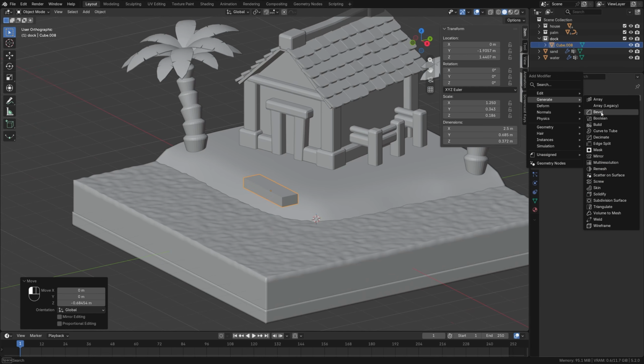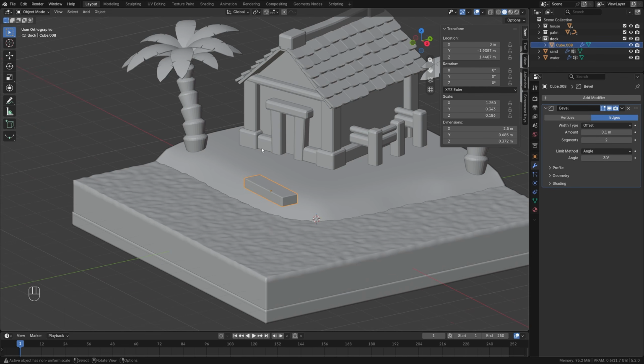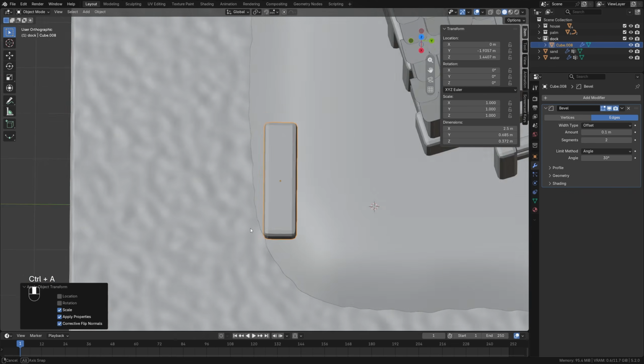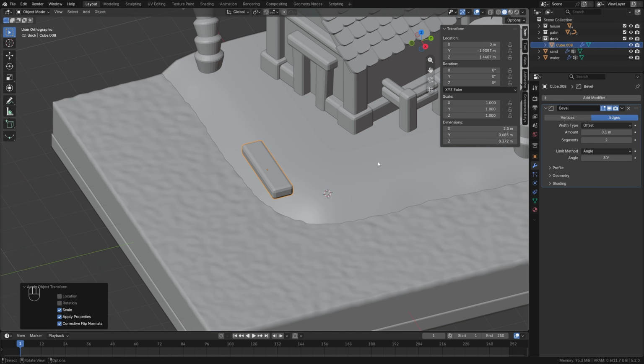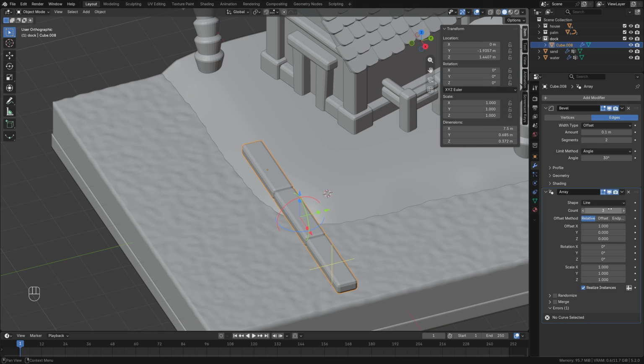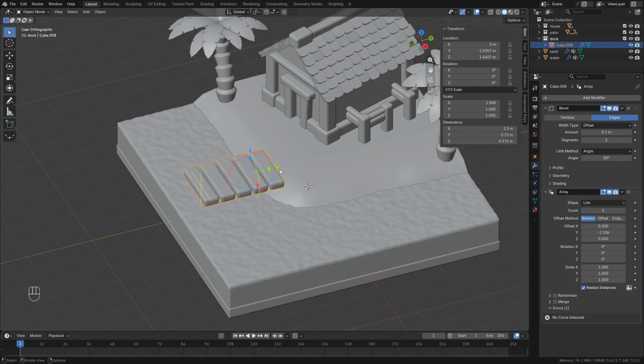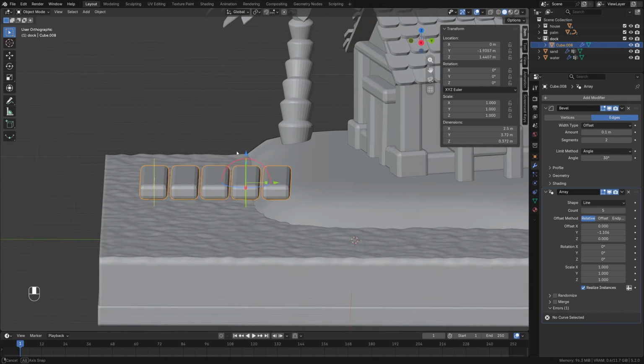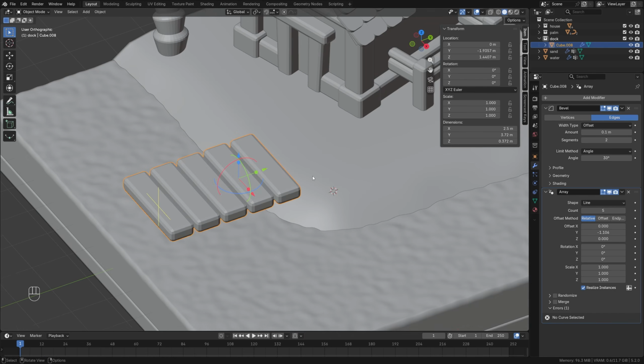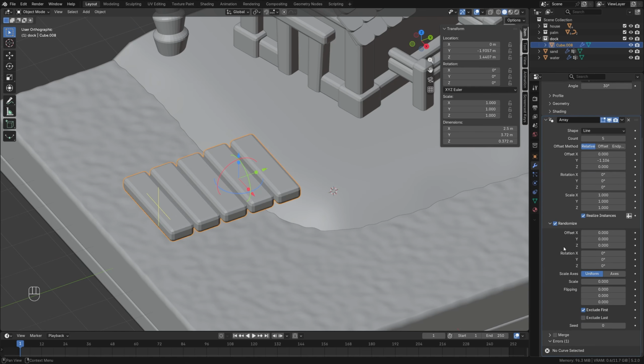Immediately we will assign for it the Bevel modifier, 2 segments. Apply the scale parameter. We see what turns out, and further we duplicate with the help of the array modifier. Here 0, here -1, you can even a little bit more. 5 planks. Well, roughly to the following sizes we will have our dock. Not bad. And as usual, variation is needed.